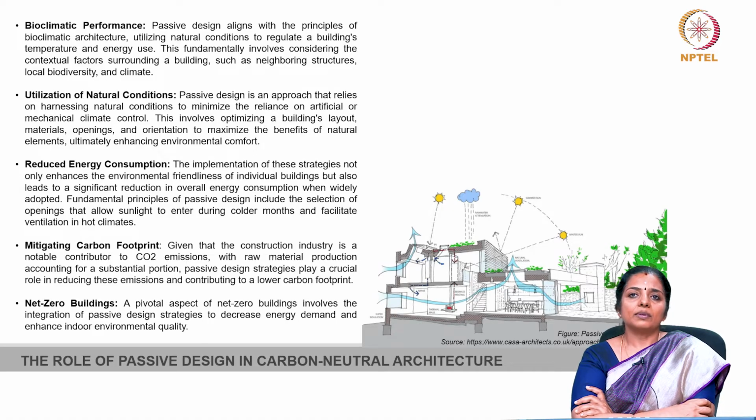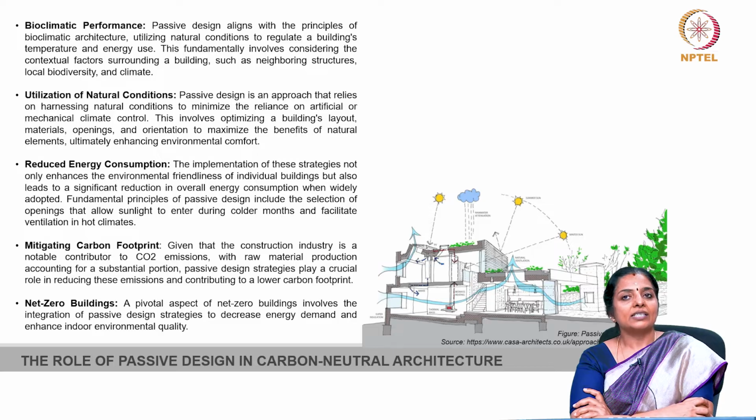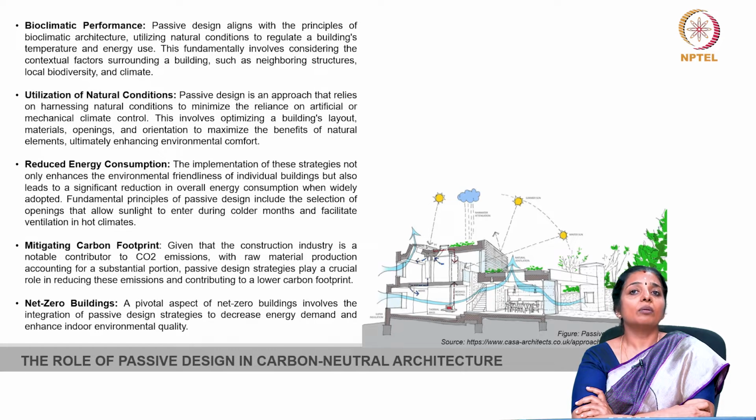The key principles include selecting openings for sunlight in colder months and facilitating ventilation in hot climates, but at the same time optimizing the openings to ensure less solar gain. Passive design plays a crucial role in mitigating the carbon footprint of the construction industry, a significant contributor to carbon dioxide emissions. Integration of passive design strategies is pivotal in achieving net zero building by reducing energy demand and improving indoor environmental quality.